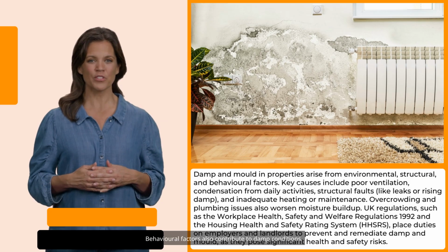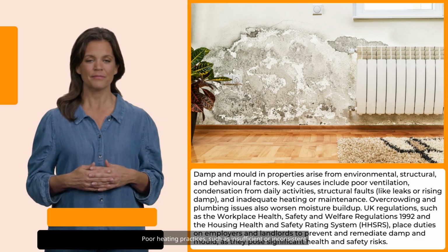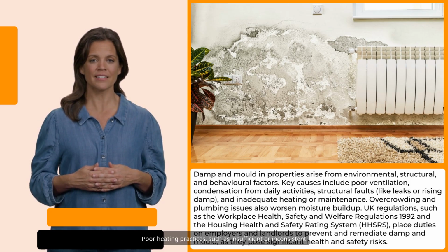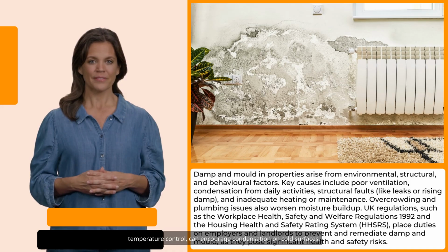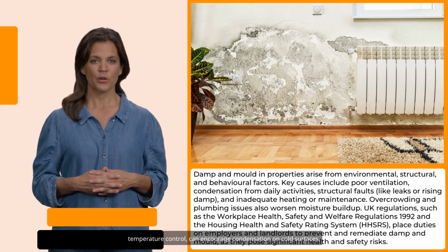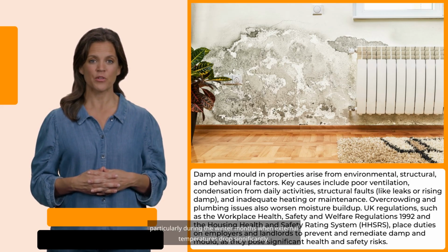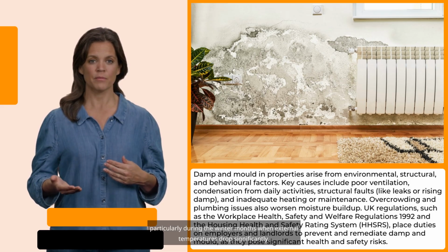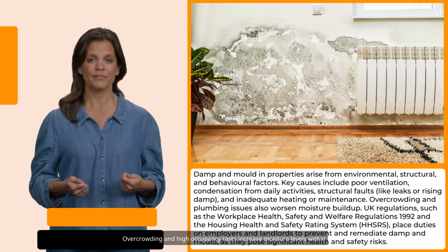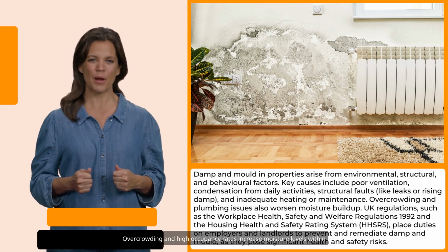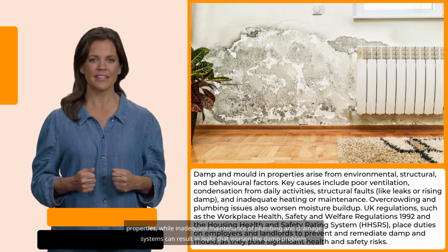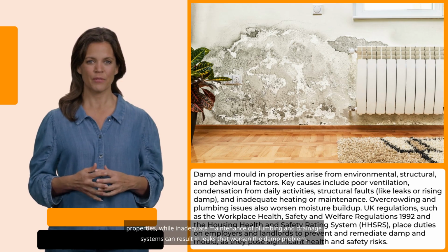Behavioral factors also contribute to damp conditions. Poor heating practices, such as insufficient or inconsistent temperature control, can encourage condensation on cold surfaces, particularly during the winter months when external temperatures drop significantly. Overcrowding and high occupancy rates increase moisture levels within properties, while inadequate maintenance of plumbing and drainage systems can result in leaks that worsen the damp problem.